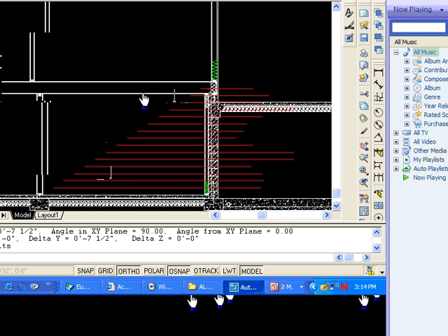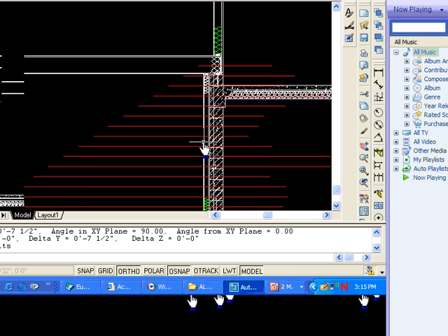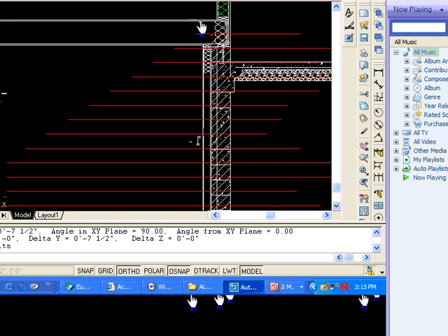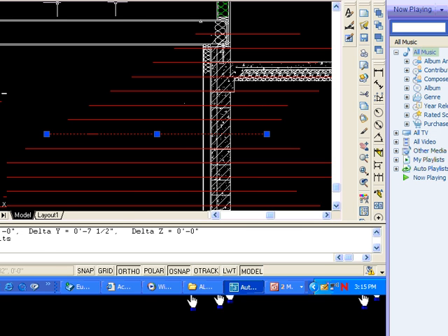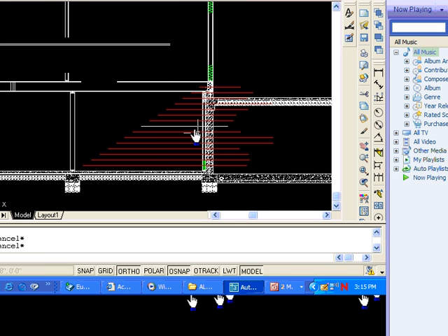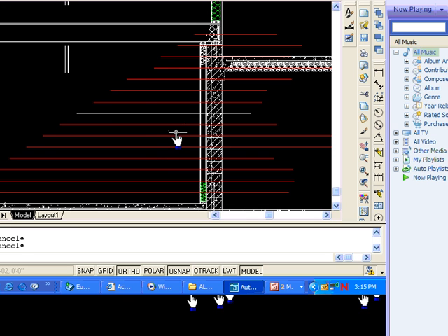So we'll have 8 risers down to the platform, and then 8 risers down to the floor. That's what my plan is going to be. It doesn't have to be that way. But what I have is 1, 2, 3, 4, 5, 6, 7, 8 risers. So this line right here, I'm going to put it on a different layer. That doesn't look halfway, but I'll count 1, 2, 3, 4, 5, 6, 7, 8. It is. Okay, it's just an optical illusion.